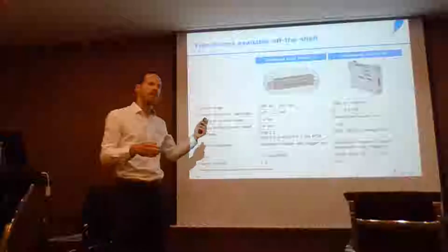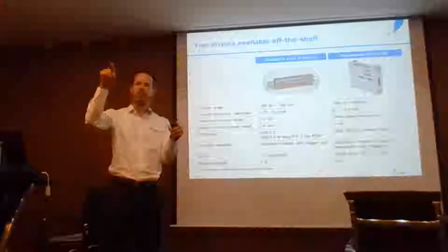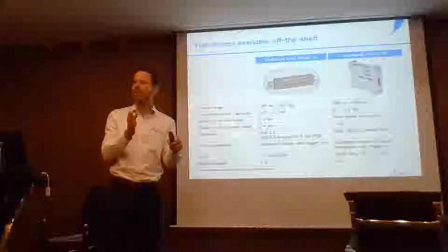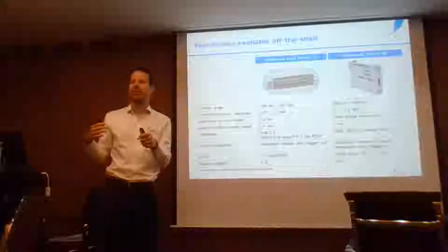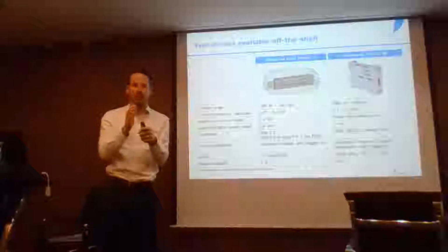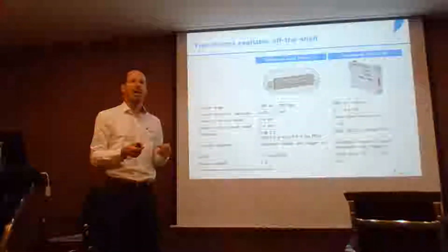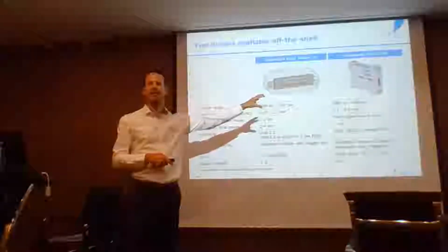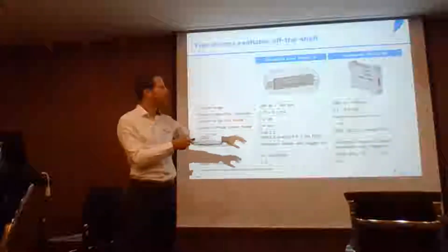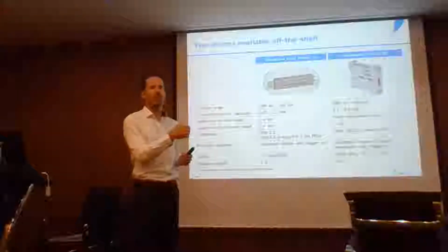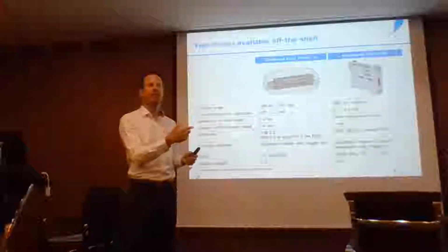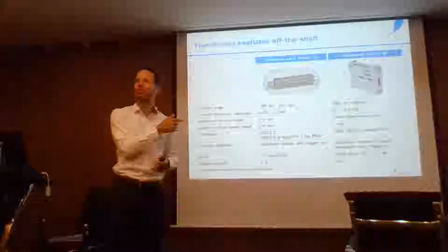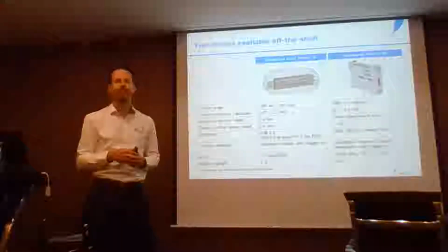So in one of the demos I'll show you later, we have a sawtooth pattern, and the trigger comes from the FPGA, which controls also the camera. So the lens always starts at the same trigger, so you can synchronize a waveform when the driver is not the master, like the slave. So if the trigger comes in from the camera or from the PC, then the lens can follow that signal and be synchronized by using the input trigger to start the waveform.